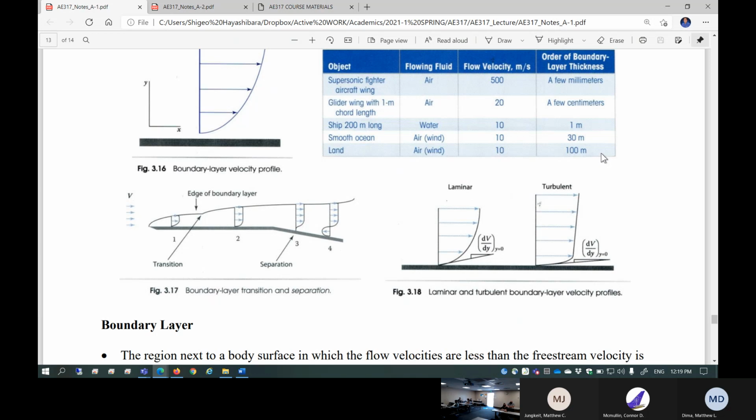Nothing makes sense. And then the car is not moving. You have to move the car. Well, that means I have to put a conveyor belt on the ground and turn it on. The car is moving, the boundary layer is sucked up, and ground vehicle wind tunnel testing is not easy. It's one of the most difficult wind tunnel testing setups.